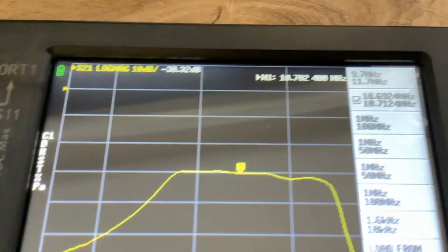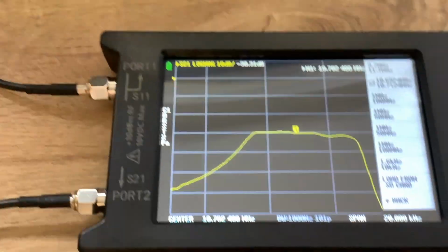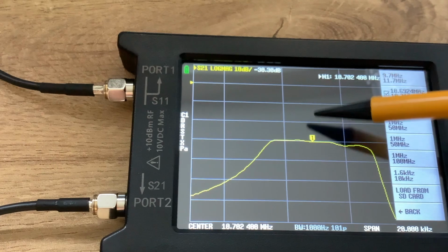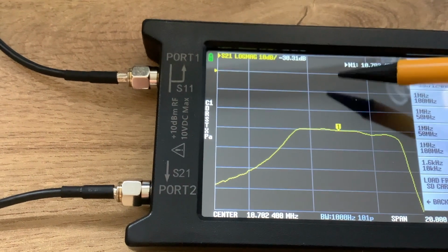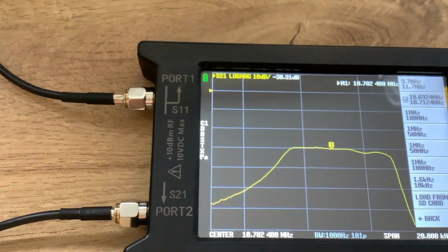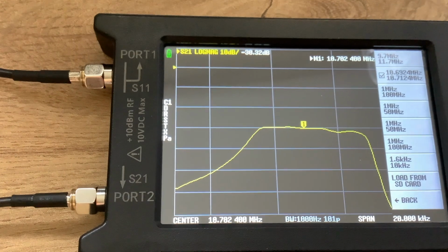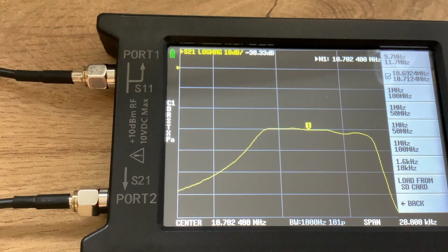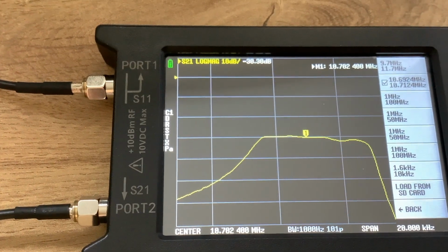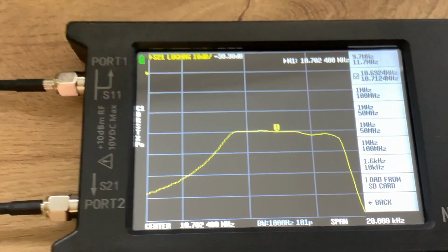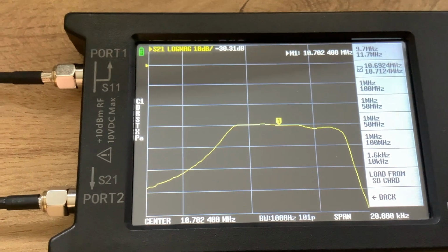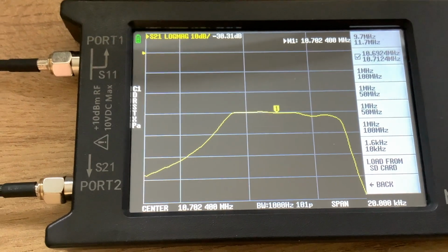Now you will notice, if I can balance this down, I'm not sure I can very easily, but just to show you clearly, the insertion loss is horrific, but of course it's going to be, because you're dropping over 1,000 ohms worth of resistance of your signal. But that's not going to bother us, because we will be swapping out all that convoluted resistance network at the beginning and replacing it with a so-called lossless impedance matching system. And I think this time I'll probably go for a good old tried and trusted conventional transformer.